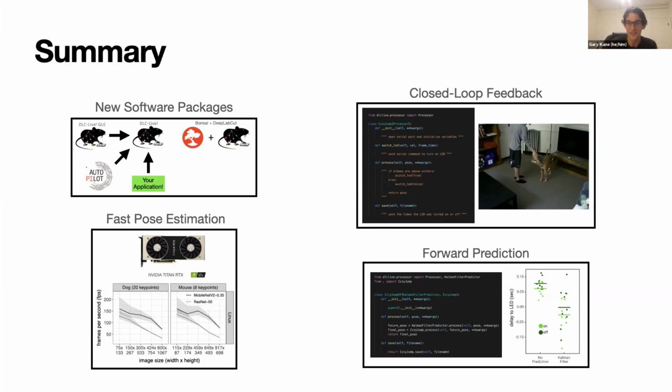The Kalman filter aspect is just a small trick to eliminate noise. If you just take those raw values, then especially in the derivatives, when you're calculating velocity and acceleration, any noise that's in the position, which isn't too big of a deal on its own, can get really amplified.